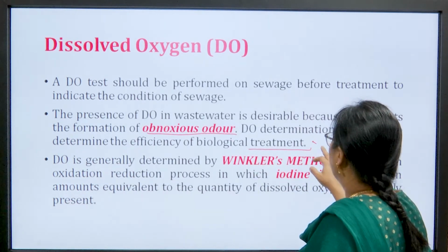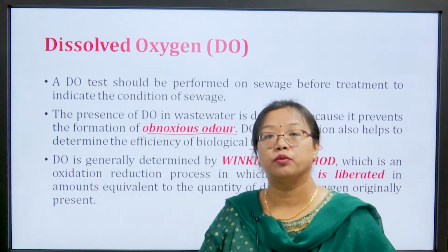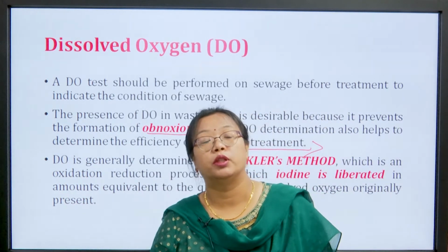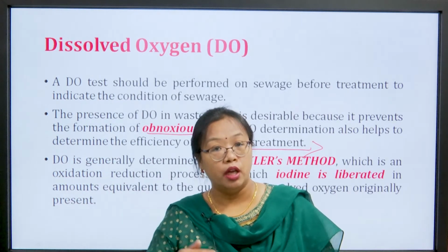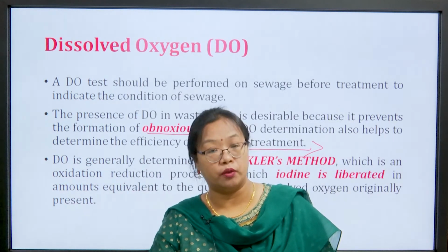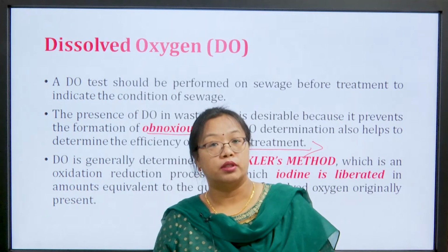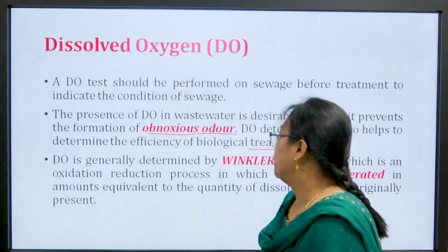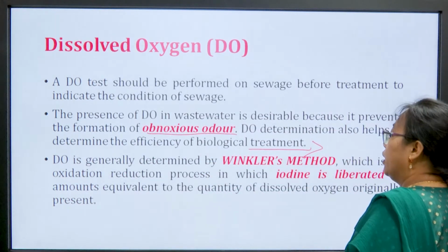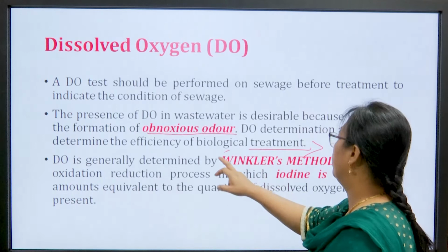So, this DO is actually very important, because when you measure BOD and all, this is all done through DO only. What is actually BOD? You will measure DO at a particular stage and then see how much is being consumed, right. So, DO is generally determined by Winkler's method. This is very important,